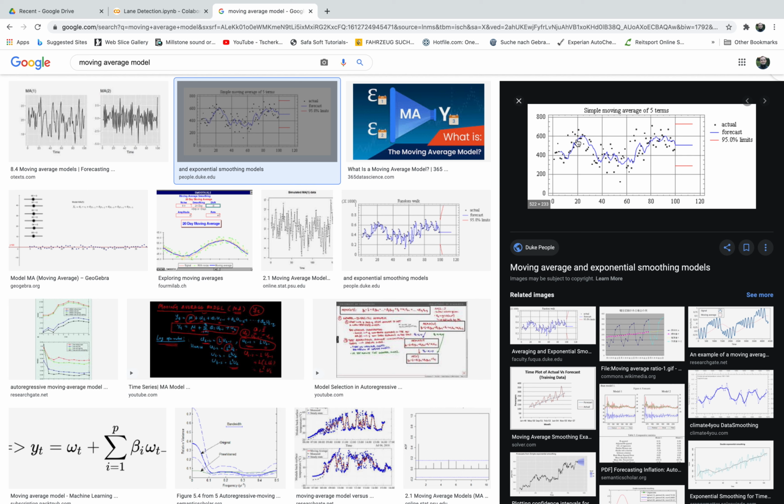So if we apply the moving average model, we might miss the sharp left or sharp right or sharp change in the curvature. We'll see that later in the simulation if we change this moving average window size, because if we change the window size, we will see how much we are smoothing. You would end up with a trade-off between canceling all the noise and having a stable estimation, but also missing, as I said, sharp curves or curvatures.